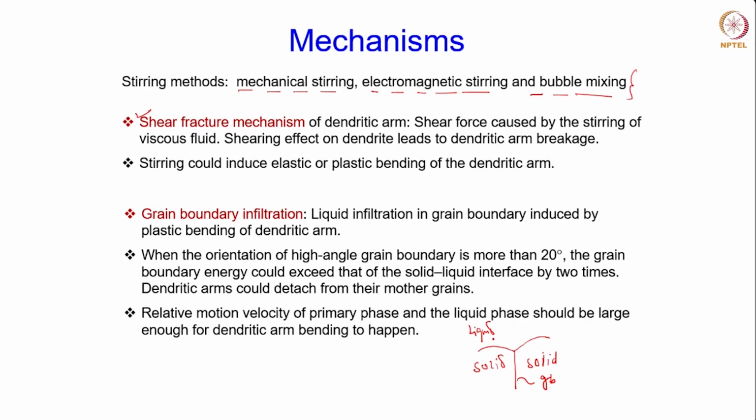So now the surface tension of the liquid will form an angle here with the grain boundary, and this angle is known as the dihedral angle. So now if I only take the surface energies, it will be like this.